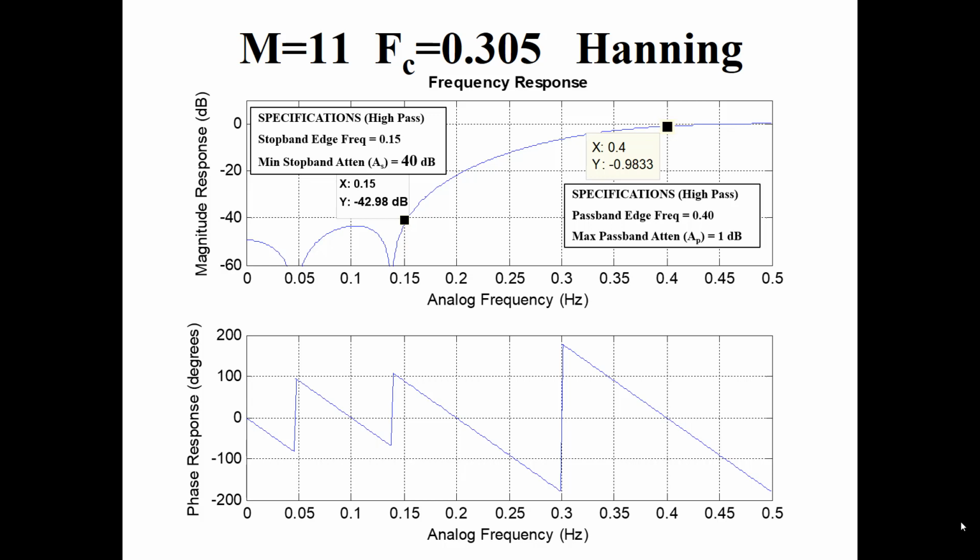Again, we use tables and things to choose our window function. We set our cutoff frequency based on the pass band and stop band edge frequencies. We adjust the filter length to get the transition widths we need, and usually the technique itself will give you a design that's pretty close. And we have to either play with it a little bit to make it a little bit better, or explore whether we could achieve the same results with a slightly shorter filter through an iterative process.